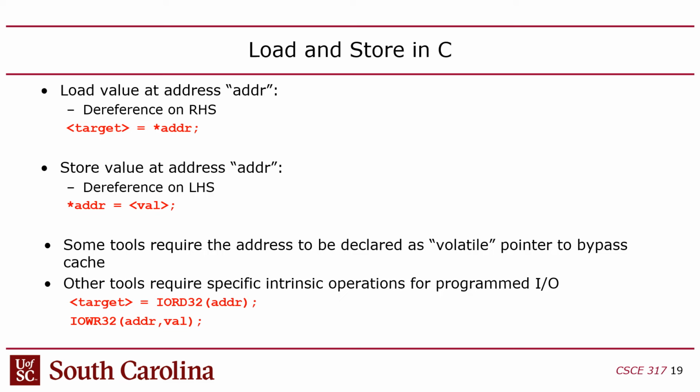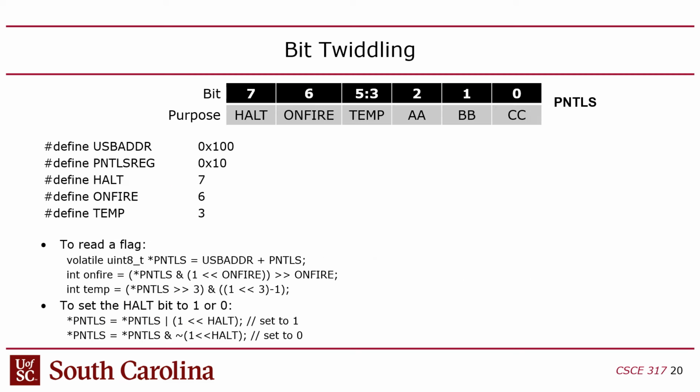But basically, the I/O write is on the FPGAs now, and this example comes from the processor on the FPGAs, the Nios II processor that you all used in 313. In that processor, the I/O write 32 corresponds to the store I/O instruction, STIO. And again, the purpose of that is to bypass the cache, if there's a cache.